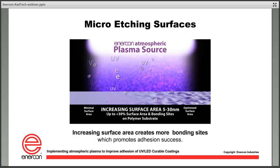So if you can envision here your coating being laid out over a more roughened surface with more peaks and valleys on it, you've actually created more physical surface area for that to grab onto, and you've also created an opportunity for more polar groups for that ink to adhere to as well. While you're not actually changing the substrate itself in any kind of physical form, you're not weakening it in any way. This is, once again, keep in mind, an extremely microscopic photo of the surface. It also helps you with